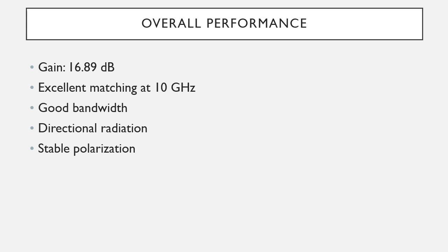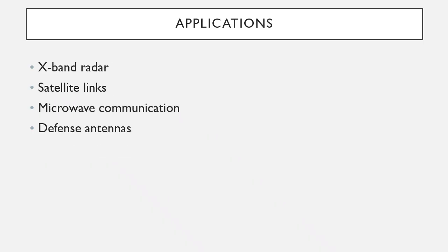To summarize, the antenna shows high gain, good bandwidth, excellent matching, directional radiation and stable polarization at 10 GHz frequency. Applications: such antennas are widely used in X-band radar, satellite communication, microwave links and defense applications where high directivity is required. And thank you.